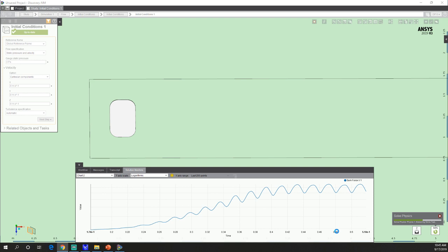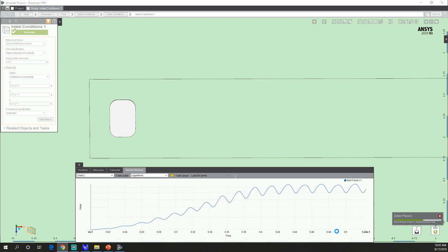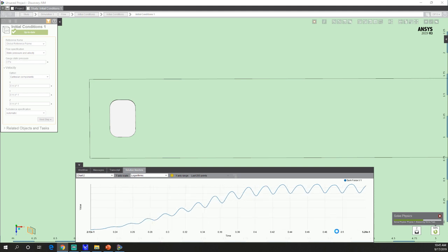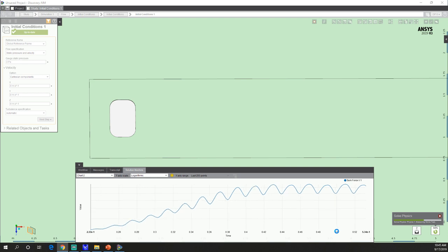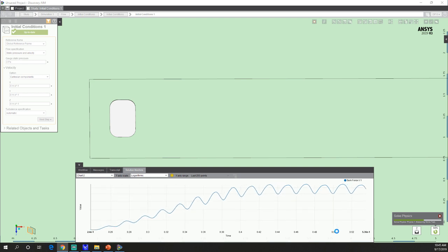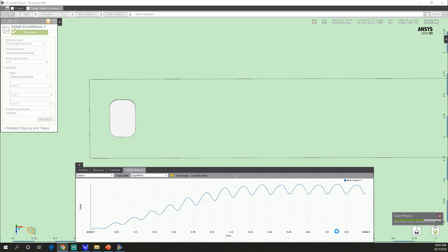With ANSYS, we don't save every single time step automatically. There's options to save, like a small, medium, large bucket of how often you want to save. I think the default is medium. So it probably takes your entire duration and maybe saves 200 points or so in between.